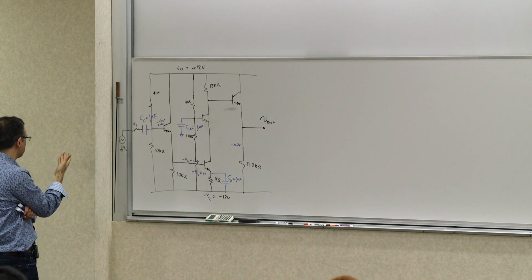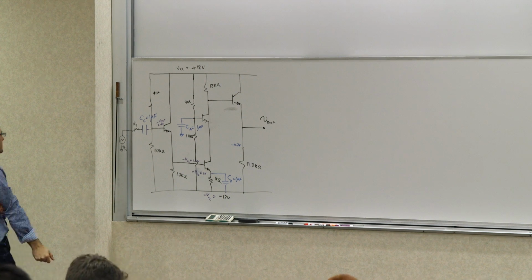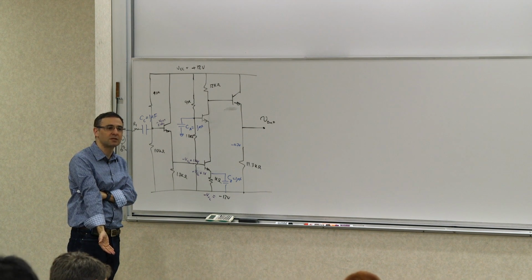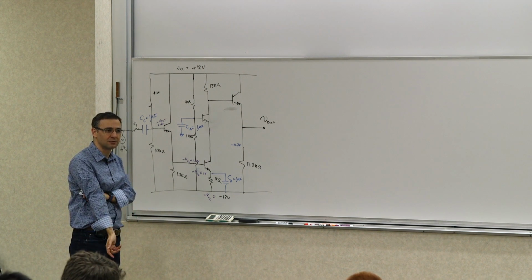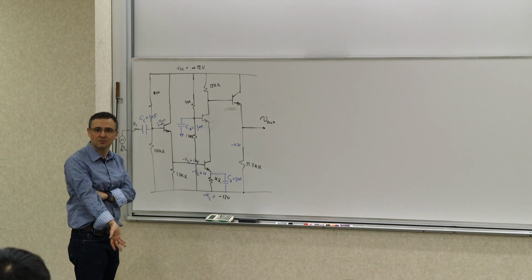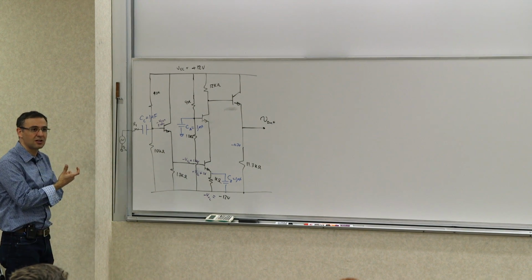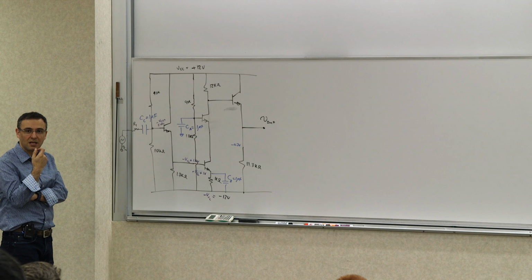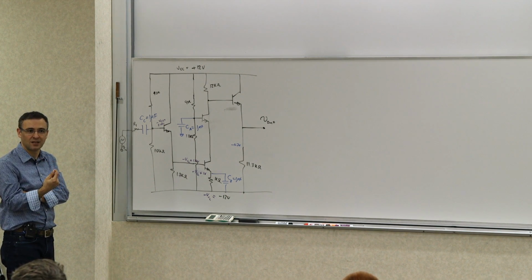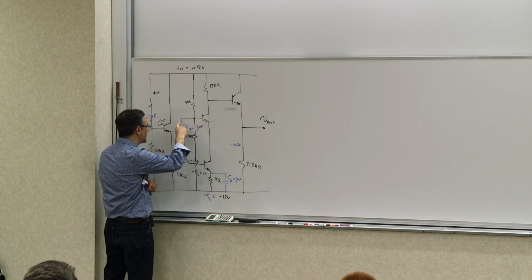So now this can work. This is a legit design. We just picked some capacitors arbitrarily. So we want to look at our low frequency, high pass cutoff, omega L. We want to estimate that. We've done a lot of estimates of omega H's, so we're not going to worry about that. These are the three capacitors that determine the omega L. How do we know? Because if you make them short circuit, the circuit becomes closer to what it should be. When you give them infinite value, that makes the circuit better.